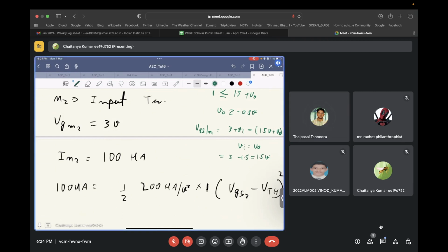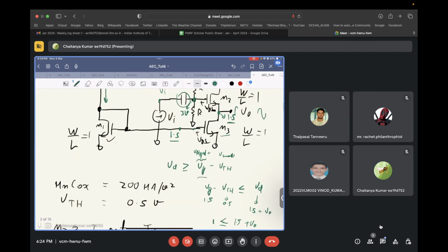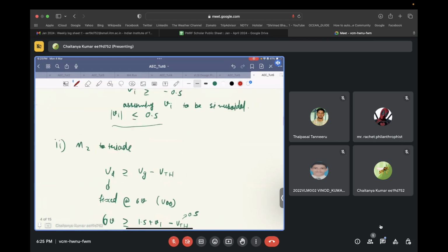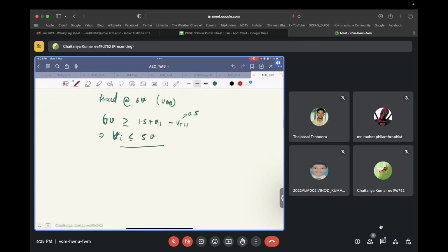Okay, so here, since your gate source voltage is not changing, your transistor can't go into cutoff. Even if there was some output resistance over here, let's say of value Rs, in that case also your VGS change will be very small. It will be basically input divided by 1 plus gm times Rs. So while doing the swing limit calculations, you can